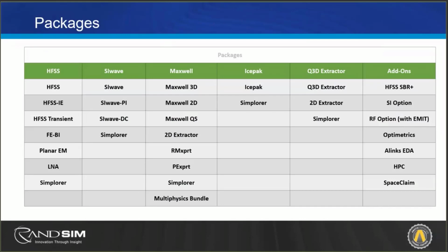Of course, there is SpaceClaim as well, which is another tool. For anyone that doesn't know it, it takes in geometry, let's say like a STEP file, and makes it simulation ready. A lot of times when I'm taking in a STEP file from a client or a customer, there could be issues with the faces.